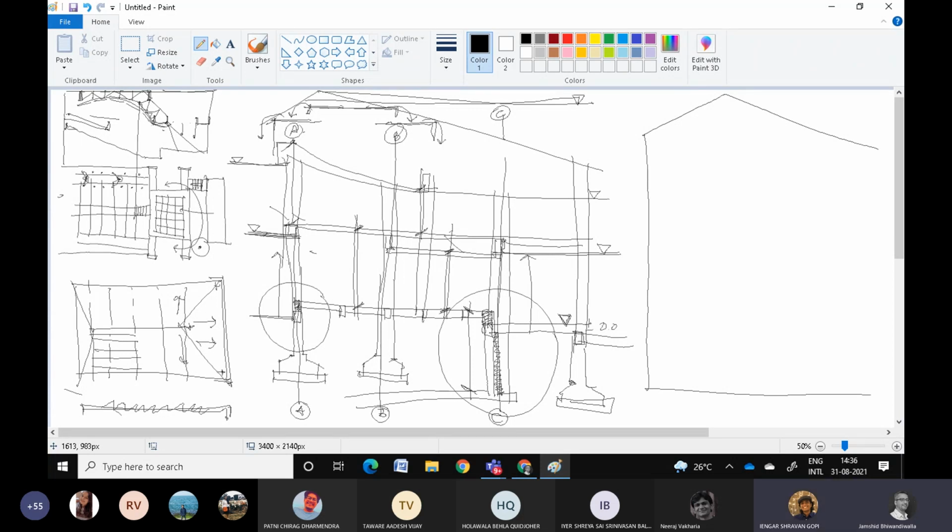Am I clear? In a section of my first bay, I don't show a staircase that's all the way at my third bay. Of course not. Why will you show that? It will unnecessarily confuse the person from where you're actually cutting the section. So things like staircases, no. All I'm saying is that structural members like columns, maybe lintels, maybe beams, if they are to be shown, could help in order to understand the overall structure of the building. Clear?